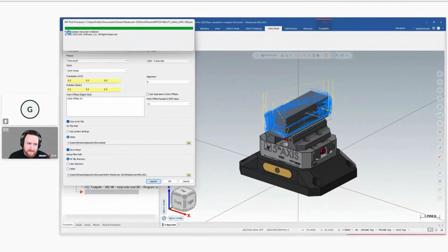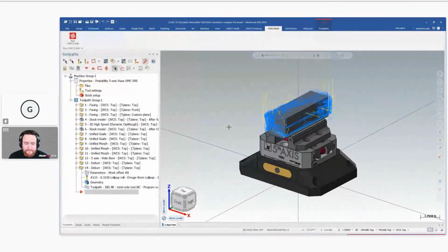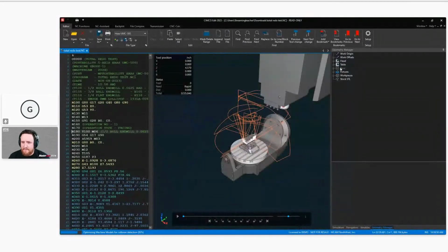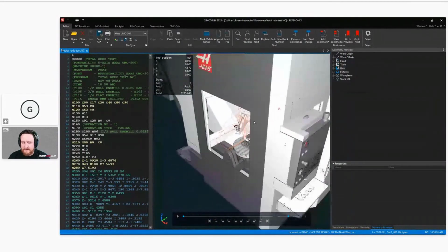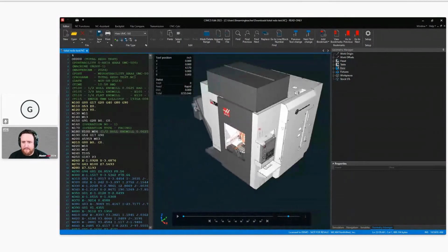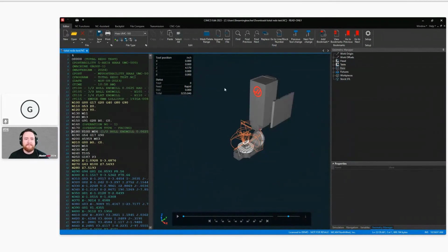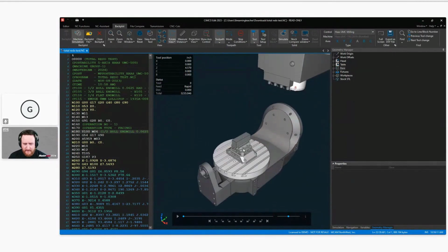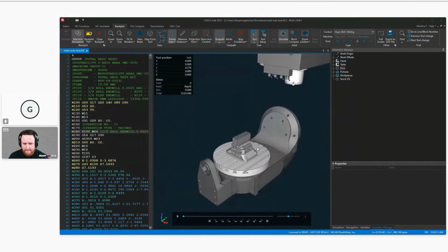So you'll see it executed the post processor. And then here we get this window, and I have my base turned off, but again, that is part of the simulation right there. I like to turn that visibility off so that it's not in my way. And a lot of times I'll turn the toolpath motion itself off so that I can see a little bit more clearly.